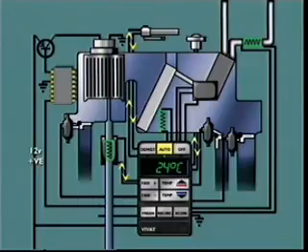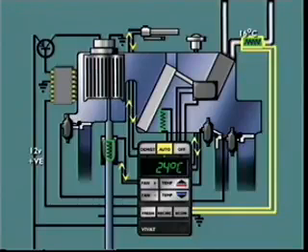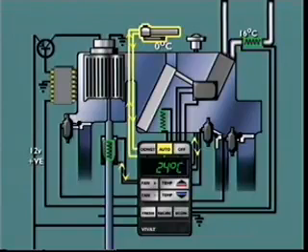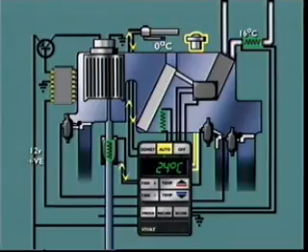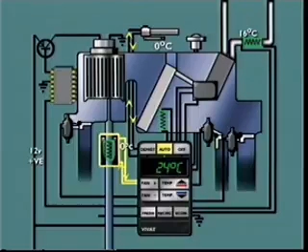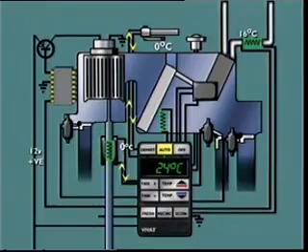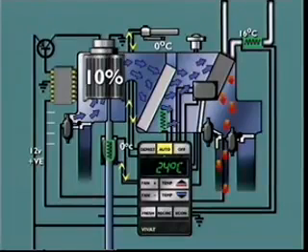For example, if the electronic control unit registers the following readings: coolant temperature 16 degrees Celsius, ambient air temperature 0 degrees Celsius, sun load 0, cabin air temperature 0 degrees Celsius, the heater tap will open fully, the blend door will move to maximum airflow across the heater core, and the fan speed will be slow and steady.